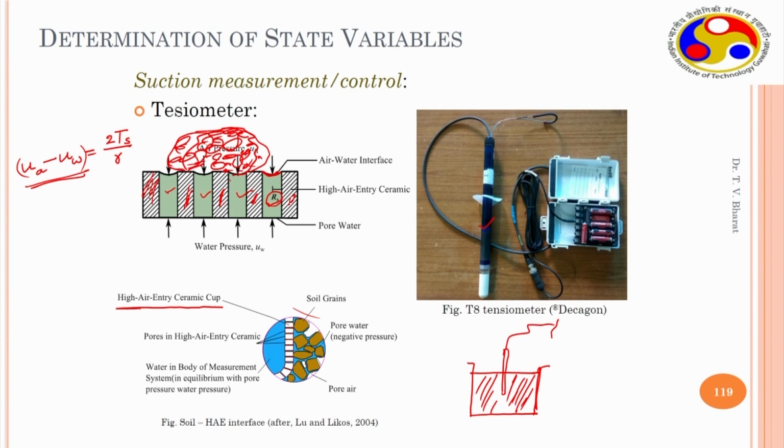If you place the tensiometer along with the EC5 or volumetric water content sensors, both water content and suction can be measured simultaneously at different equilibrium water contents within the soil mass, and one can establish the relation between theta and psi.